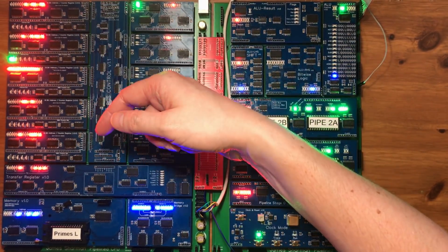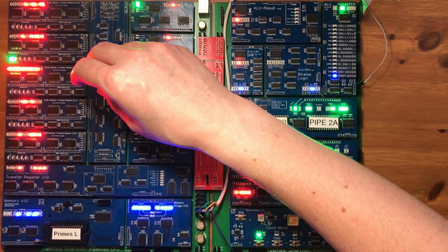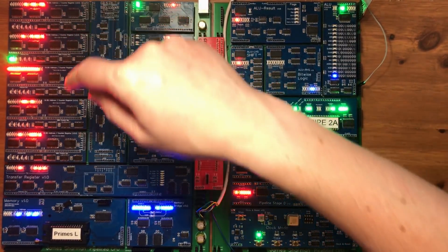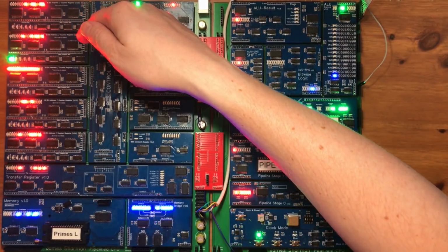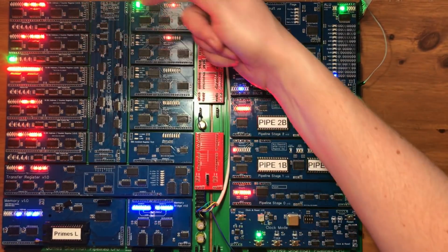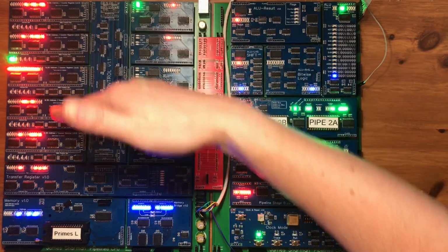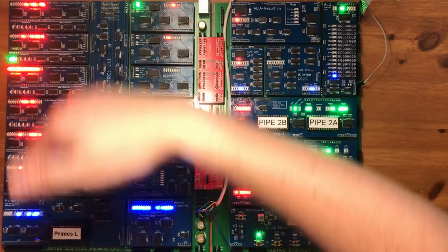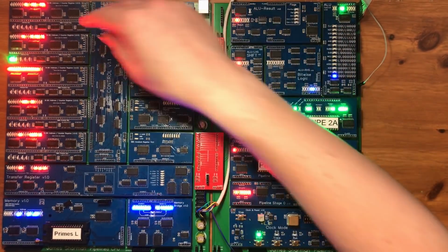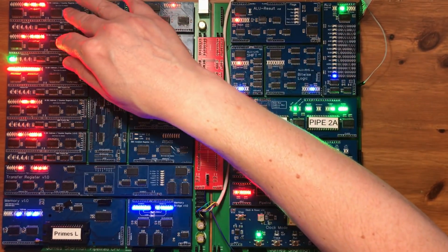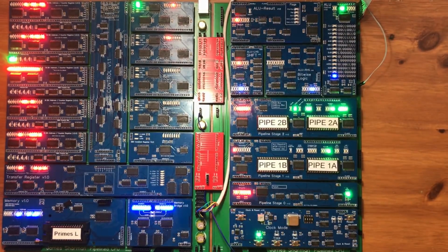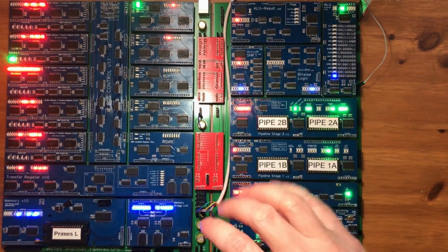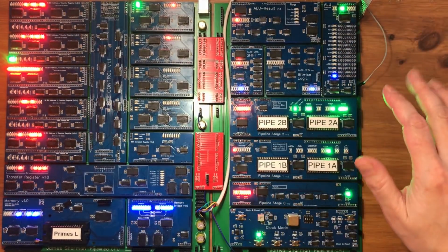If it's more complex, it would work out how to save off the program counter, set the program counter to the address of an interrupt service routine, and then it could turn the interrupt off and let the processor continue there, and then we'd have a more complicated return there that would restore the original program counter address. So we'd need an extra register here, but that's not the only change.